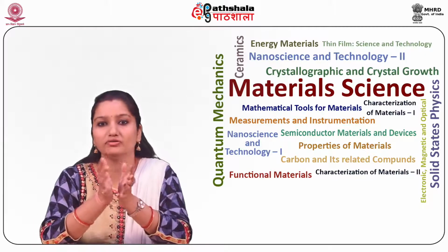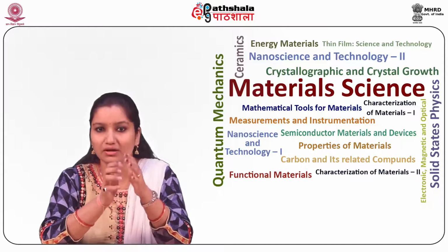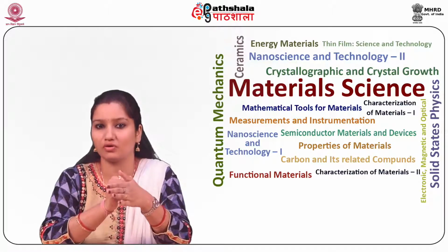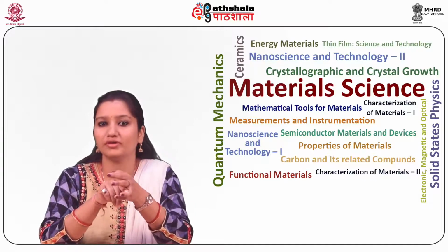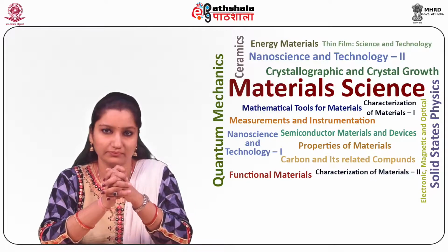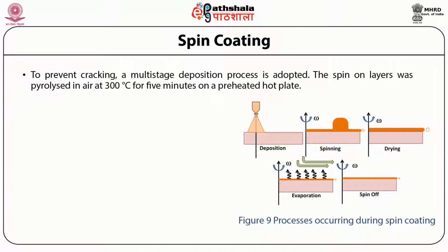Because of the large volume shrinkage accompanying the densification process during firing, cracking of the films is a serious problem. To prevent cracking, a multi-stage deposition process is adopted.